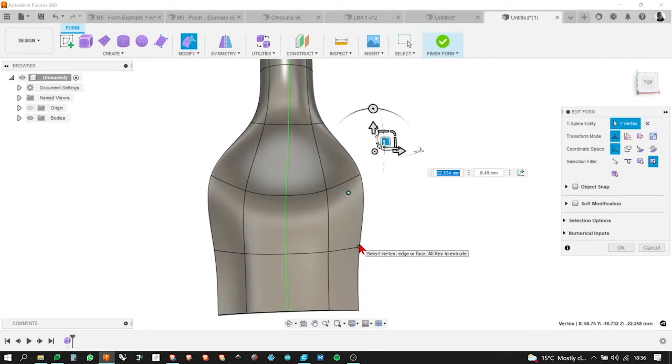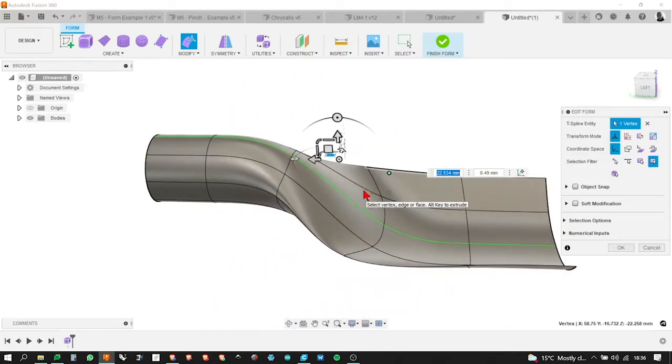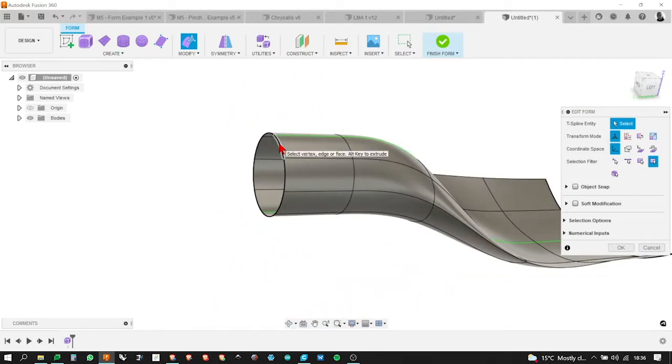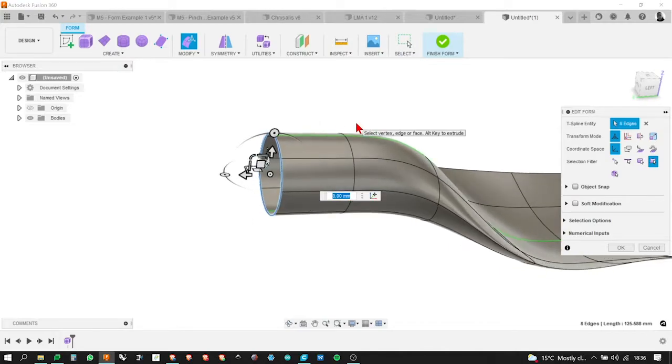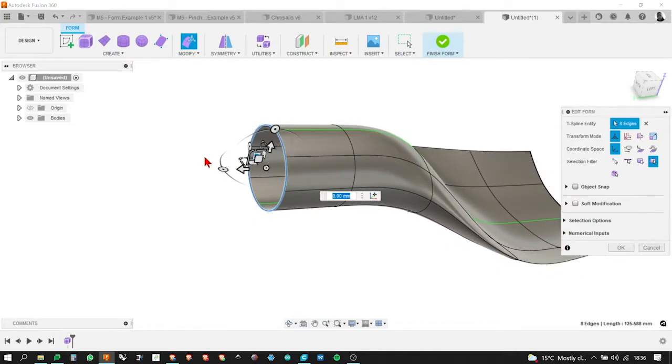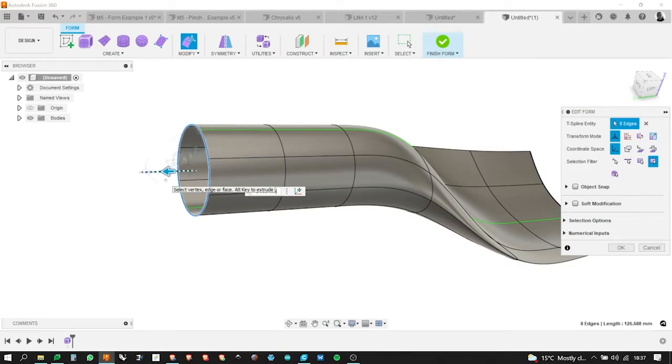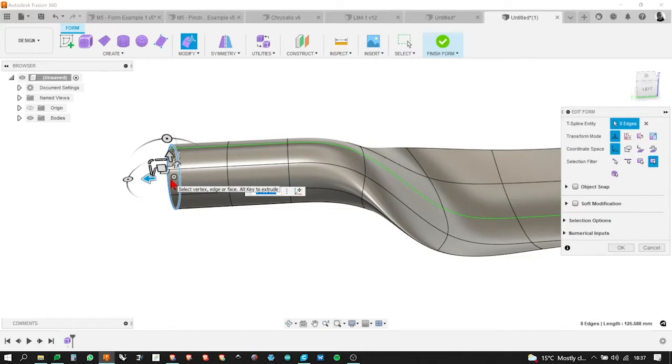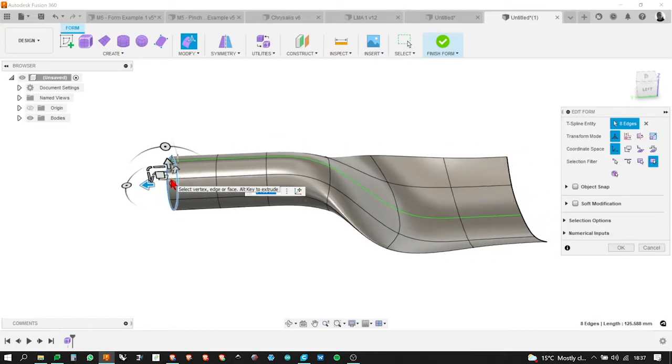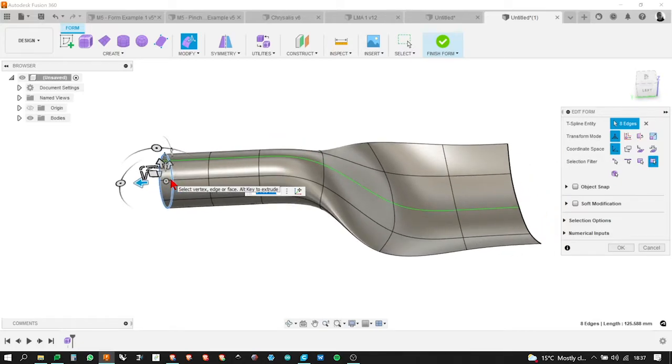You select that open face first. Let's do it again. So if I double click on this whole line, select the whole thing. Now I hold down the Alt button, and then you drag out in the direction backwards, as it were. It will automatically create another set of faces. Oh, and one more set. So add another set. So it was subdivided into 4, then it will be subdivided into 5 and 6 and so on, however many times you want.